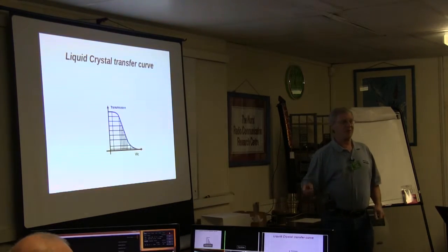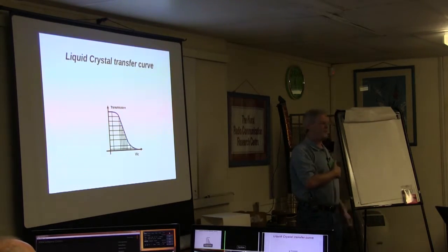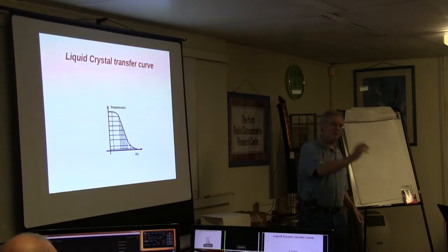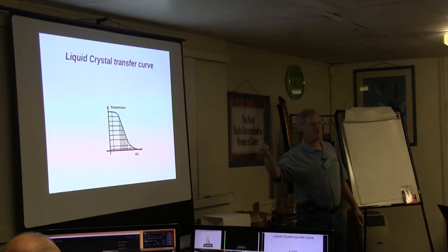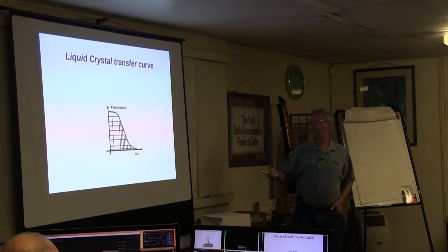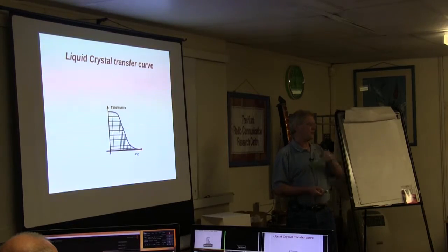And then on top of that, if you're going to use an LCD in a television system, where back 15 years ago most of the viewers were still using CRTs, obviously the gamma has been applied back at the studio. So the TV signal is already gamma corrected. And now we've got double trouble because we've got this strange transmission characteristic as well.